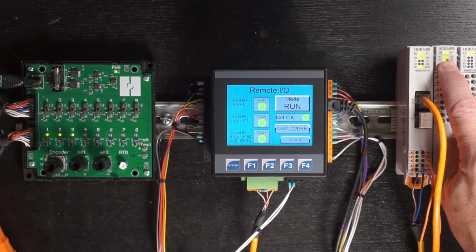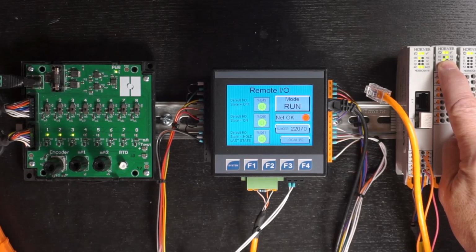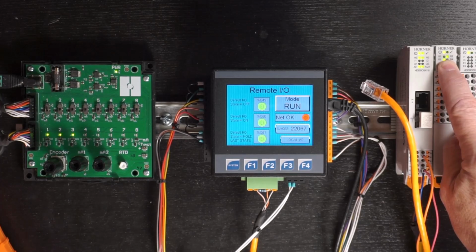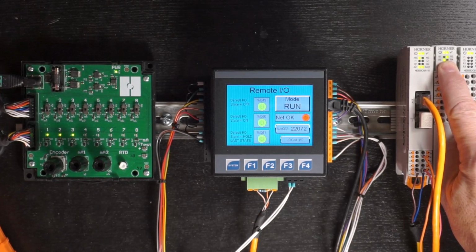Okay, now, in addition to the PLC going into stop mode, we also could lose network communications. All right, that's another possible scenario where the default I/O state comes into play. So let's pull the plug on the network. Okay, and very quickly, you can see we've lost communication based on the flashing LED. The first output is off as it's been configured, the second one on, and the third one held its state. All right, let's resume communications. And a few seconds after I plug the cable back in, we should have all solid for communication. And then once again, the outputs are following the switch.